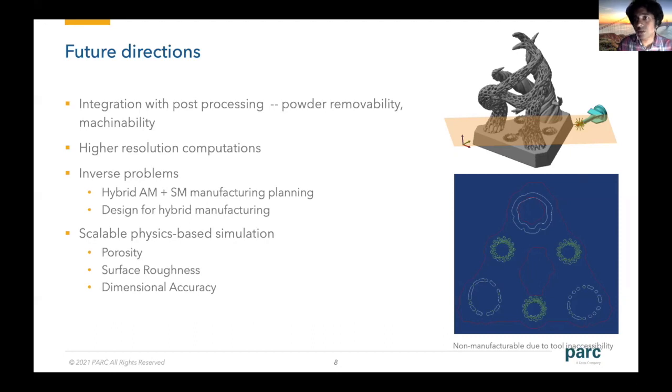So you have changed the geometry and you've changed the functionality. I would say that the part is not manufacturable as a composition of additive and subtractive manufacturing. So you're right, but without a mechanism to undo these changes, you might be changing the performance and the functional characteristics of the part, which is part of the planning problem here. Thank you.